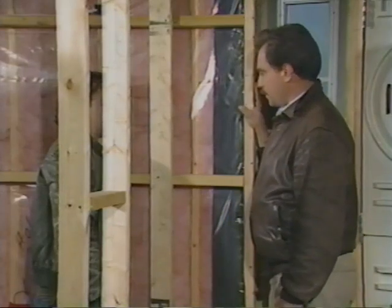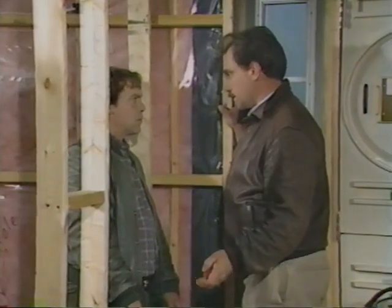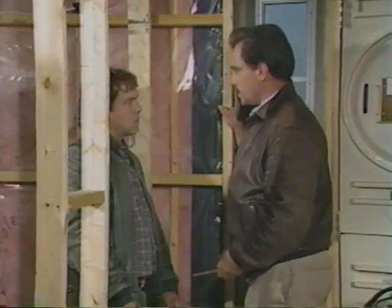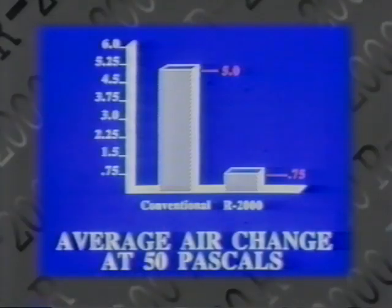All the doors and windows have been wrapped. The electricals have been very carefully taken care of at each electrical box. The plumbing stack has been sealed. All the places where we previously saw difficulty, we now don't have any. So this is the famous continuous air vapor barrier. The fact that it is continuous and that there's no air leakage is the root of lower fuel bills and good air quality and all of those things?